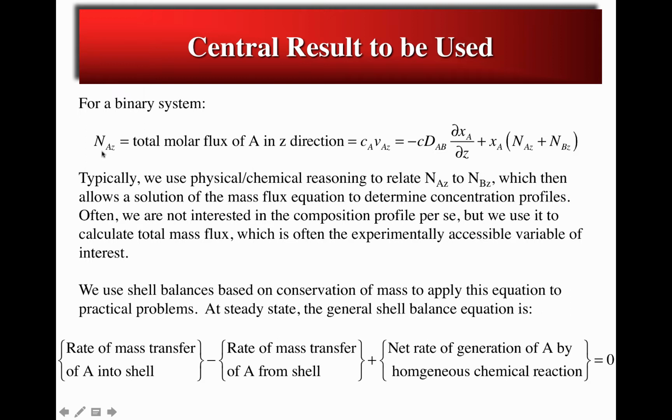However, due to mass balance considerations, typically focusing on one component is sufficient to get a solution to the entire mass transfer problem. So, for example, once you know the concentration profile of A in a system of A and B, then by its very nature you know the concentration profile of B, because, for example, the mole fractions of A and B have to add up to 1.